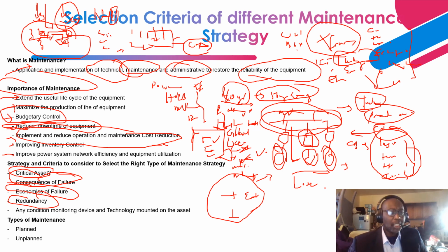There's something they call make and break. So you close the tiebreaker first, then you de-energize, you trip this incoming breaker. That's the switching sequence that you implement. For you to do that, it means that you have to look at the condition of this transformer. Is this transformer able to support all that load?